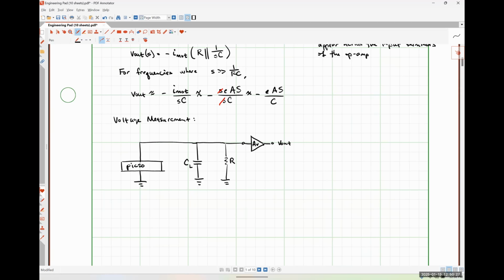So for this particular case, since we're not using a transimpedance amplifier, we can't say that our piezo element is simply shorted out on both sides. So we're going to have to deal with our AC current, right? I'm going to draw these currents in this particular direction just for making Kirchhoff's current law easier to apply.